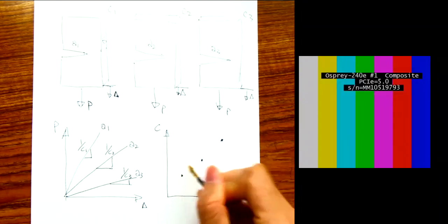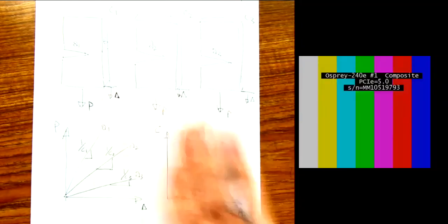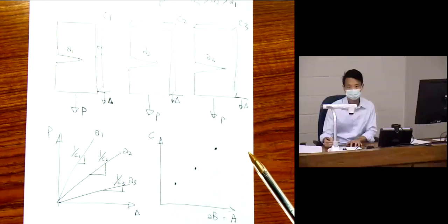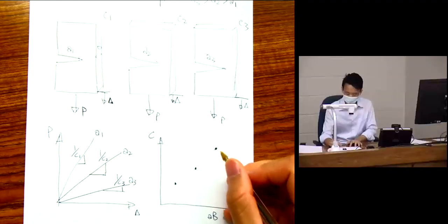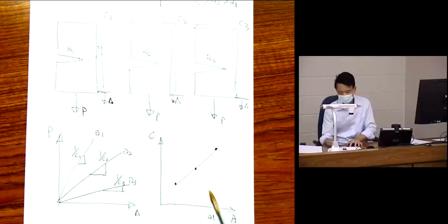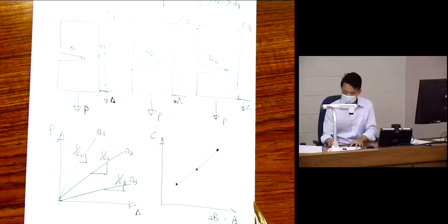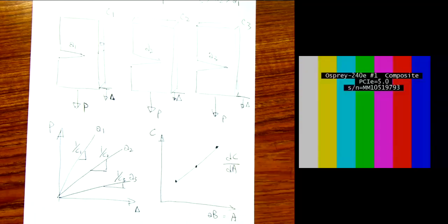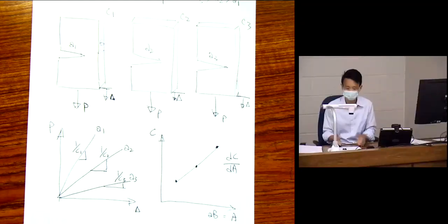So you have these 3 points, and you can make more, right? You can always do more experiments by making more copies, and then you have a more precise curve from here. So now you can draw these points up. They don't have to be linear. I'm just using this simple example here, and then you can calculate this from the experimental data. All these are experimental data. We have not written a single equation here, other than all the definitions of compliance and crack length.